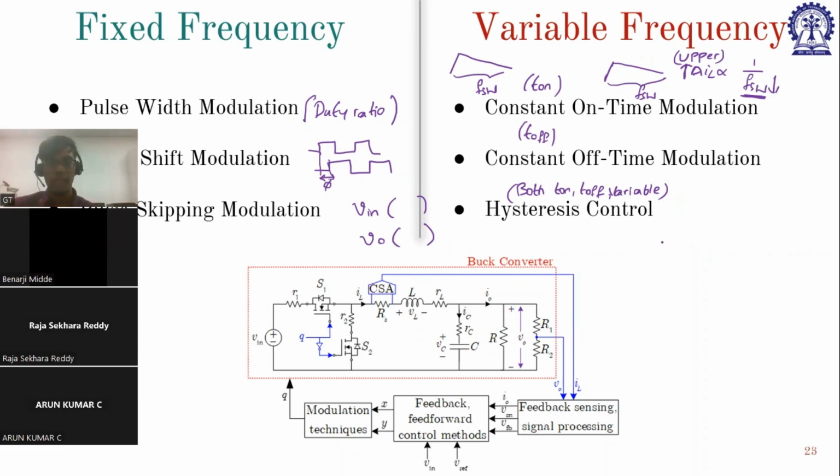One small question. What is the reason behind the efficiency improving as we decrease the switching frequency? So there is this trade-off. If switching frequency is high, then switching losses will dominate and be more, and conduction losses will reduce, because with a high switching frequency the ripple will be less, the RMS current will be less, so comparatively the conduction loss will be less.